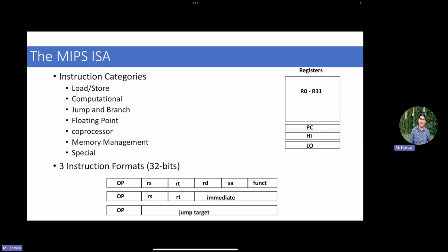To simplify the hardware while not breaking compatibility, you write your software as it is, the compiler will create the complex instructions, but we add one layer to really simplify the instructions, breaking them down into multiple ones as if we are RISC. Why? Because we want to simplify our hardware, right? That's one way that Intel is trying to get into those markets, by simplifying the hardware while not breaking backward compatibility with their complex CISC instruction set.